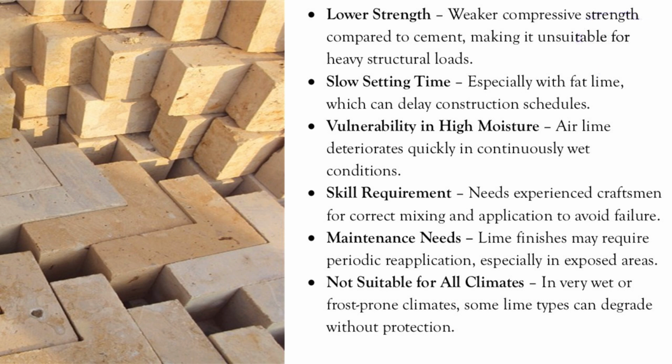Then it needs experienced craftsmen for correct mixing and application to avoid failure. Lime finishes may require periodic reapplication, especially in exposed areas. And talking about not being suitable for all climates, in very wet or frost-prone climates, some lime types can degrade without protection. And yes, with that we have discussed the building material lime.